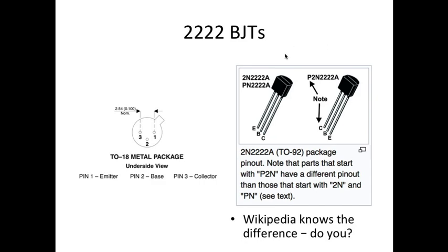There are also 2 plastic packages, and unfortunately they have different pinouts. The 2N2222A or the PN2222A has this arrangement: emitter, base, collector. If you put the flat spot on the right, it looks like it does in the diagrams.